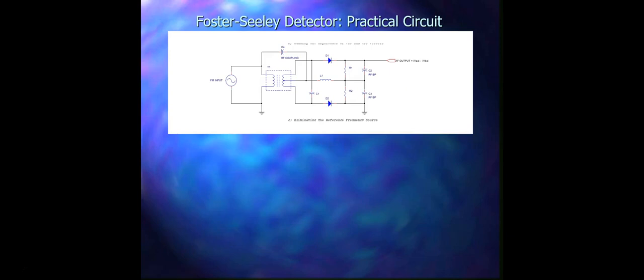There are some advantages of this circuit. It offers a good level of performance and resonance linearity, and it is easy to construct using discrete components like your inductor and capacitor. The drawbacks are that it is not suitable for IC technology, it is not very compatible, and the cost of making the circuit is also very high. And the last one, which I already told you, is the noise, and for that you can use the limiter circuit.